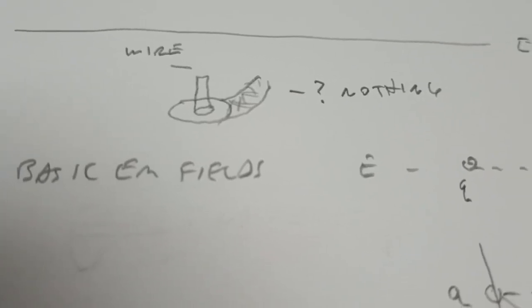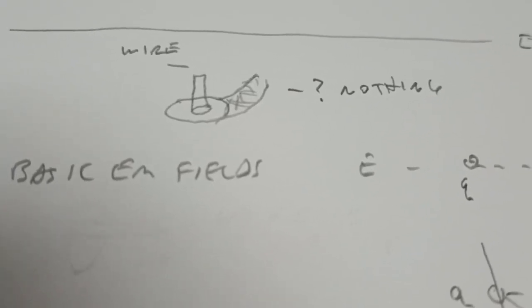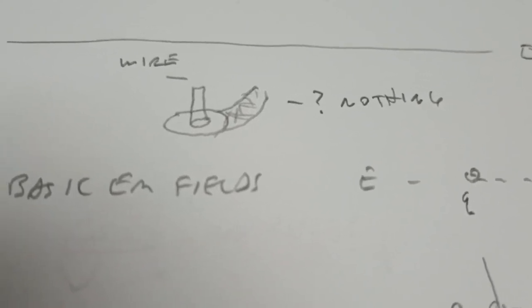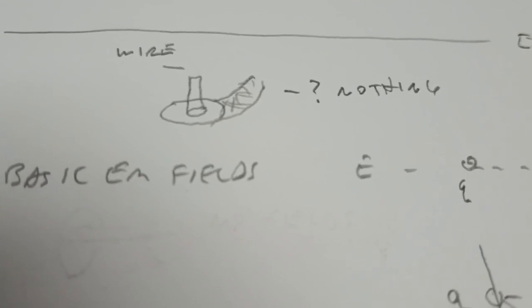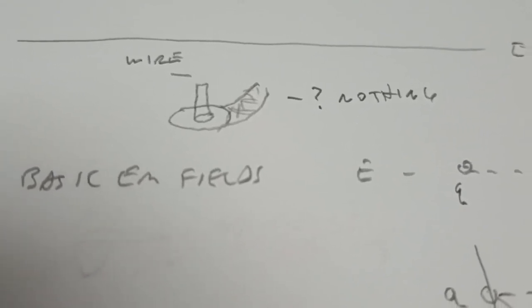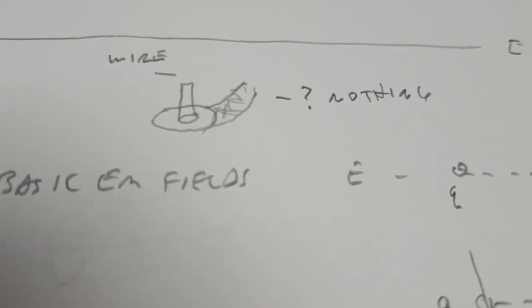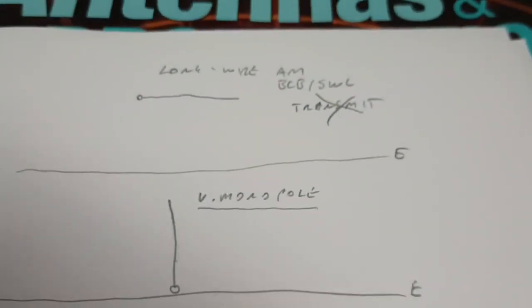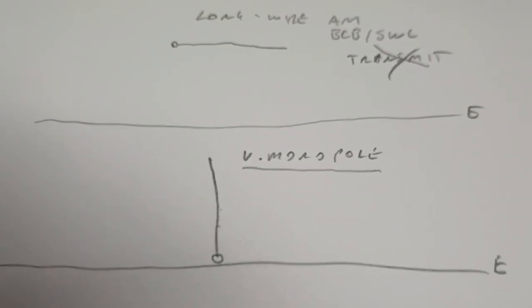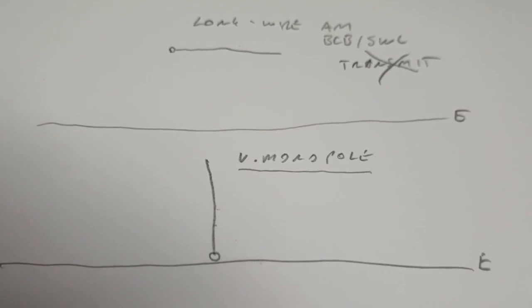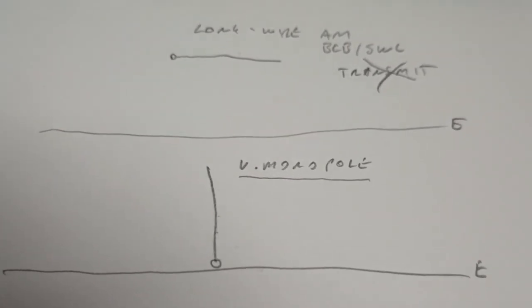That's called an open circuited transmission line. There's a little bit of capacitance added to the end because the wires are coming out. It doesn't do anything useful. It basically reflects almost all the energy back to the transmitter. It's not much of an improvement to extend that center wire like either of these. That can in theory put voltage excitation on the wire, but it doesn't work.